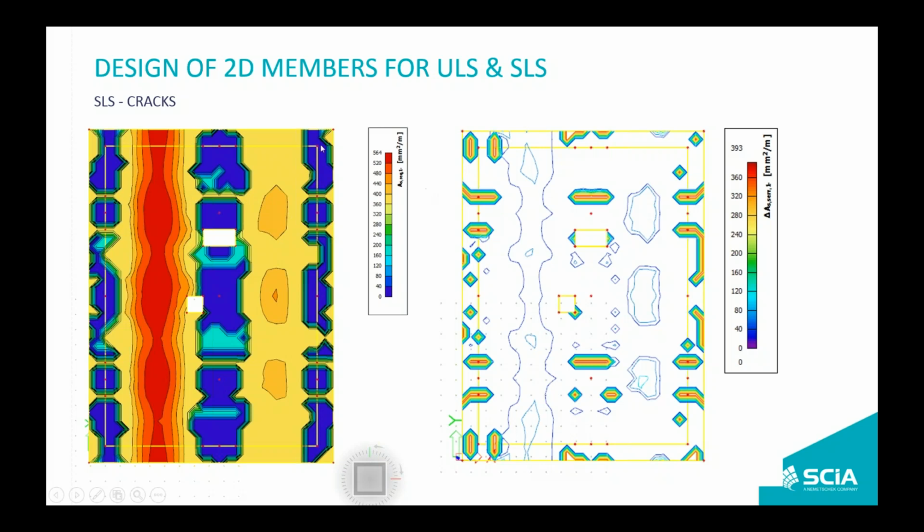checks. And you can display, as I showed on the previous slide, you can either show all these checks or all this required reinforcement design in a single image, or for example, you can only see which is the additional reinforcement designed based on the crack width. So here we can see that parts that are common in both diagrams are not based on the reinforcement design from the bending moment, but they are from the crack.